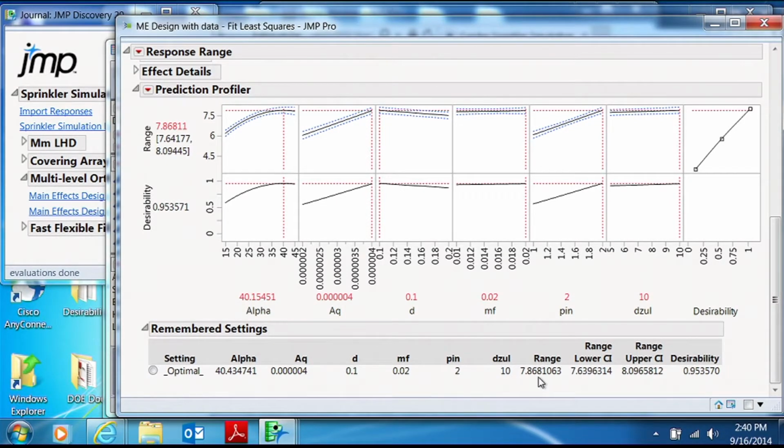Note that the first design that I did was a Latin Hypercube design with 81 runs. Essentially, what they tell you in the literature is that the number of runs that you need for a setup that has d dimensions, in this case 8, is 10 times d runs, which would be 80. So that's the standard advice.